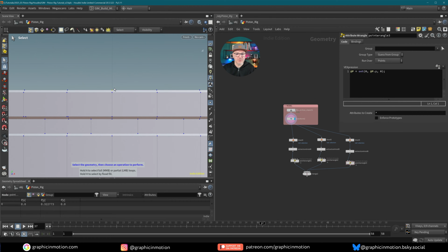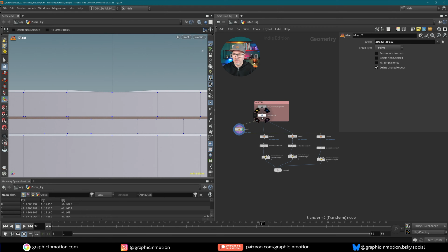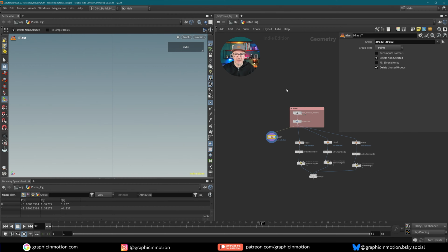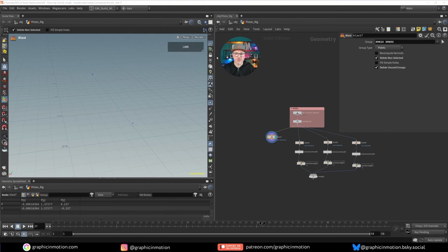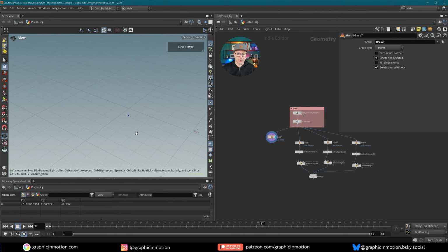Let me see whether I can grab it. Yeah, I can grab it. And now I will just blast this out. So again, I have a blast here and I actually grab 2 points. So let's see what happened here. I just want to grab one actually. Let's say delete non-selected and let's go to our perspective view. Oh yeah, of course, I didn't turn on select only visible. So I have to just delete one of these, and I will just delete the number out of my blast node, and I'm left with only 1 point.